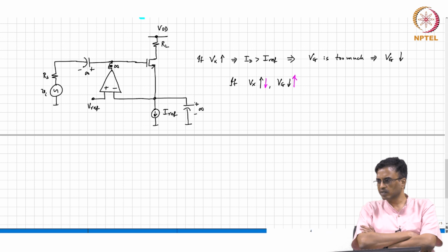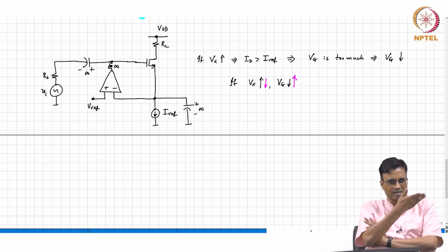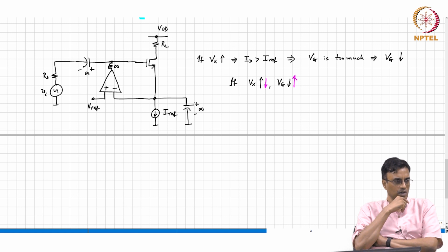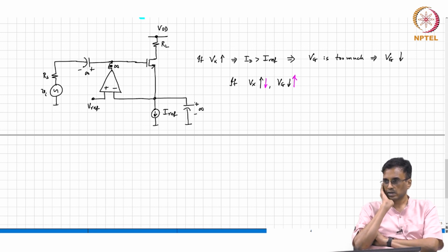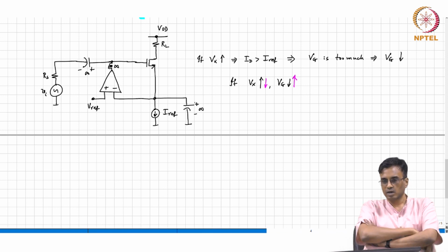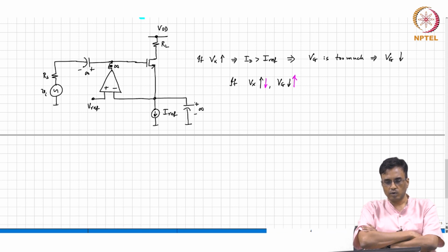On the other hand, in practice there is going to be some limit, like as pointed out before. Of course, eventually you will burn the transistor and so on. So, in reality there is a limit, but in principle there is no limit. That is what I want you to be cognizant of. And the common source amplifier, therefore, is an amplifier where in principle you can get a very large gain, because that GM can be very large, and therefore GMRL, the magnitude of the gain, is very large.